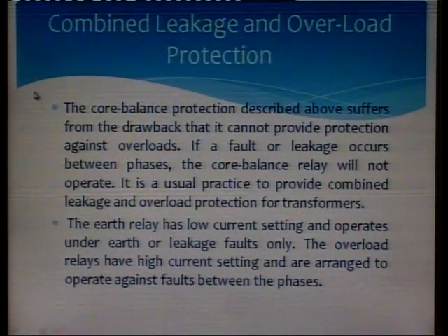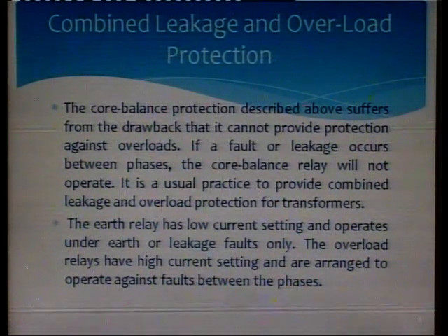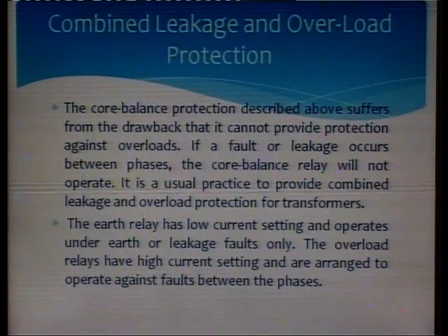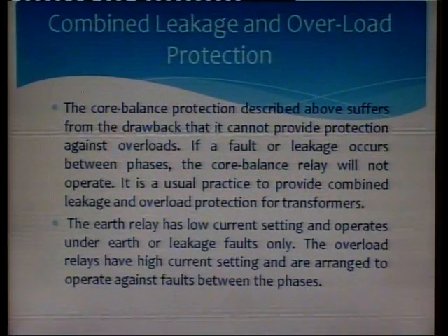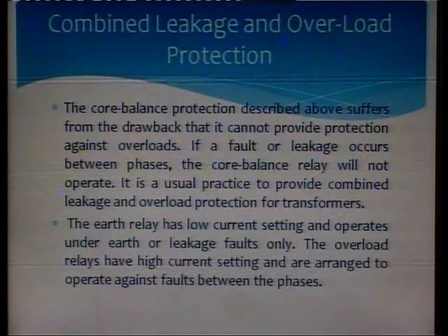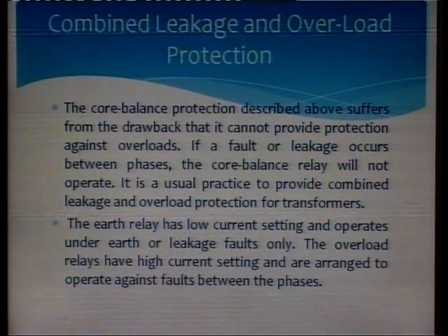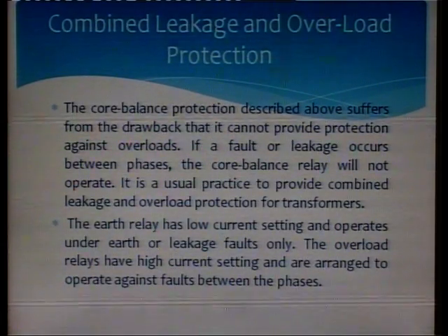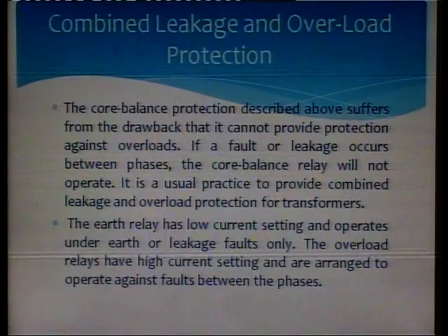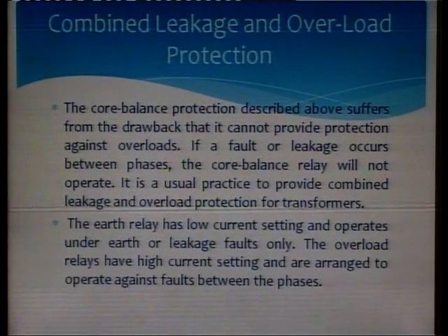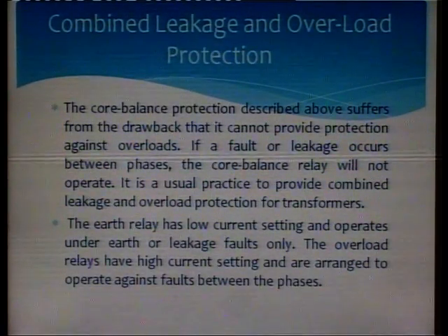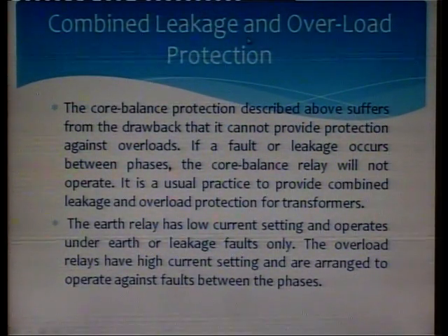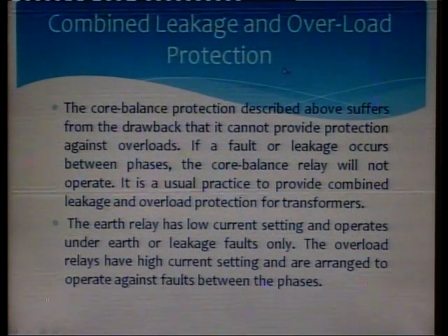Now, next is the third main protection scheme, that is a combined leakage and overload protection. Now, see the previous protection scheme, that is the earth leakage protection. This is only used in case of earth faults. So, that scheme will not respond for the phase to phase faults. So, the third scheme is used for the earth faults and the phase to phase faults both.